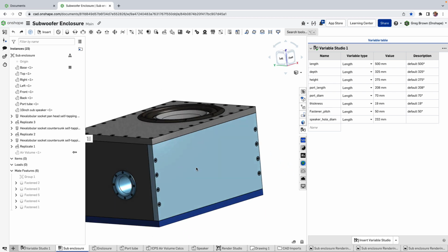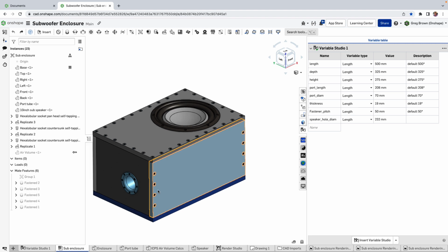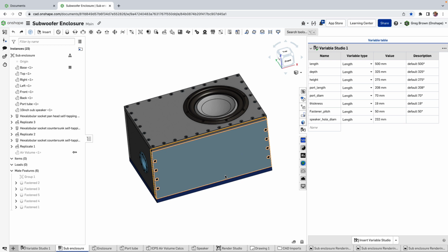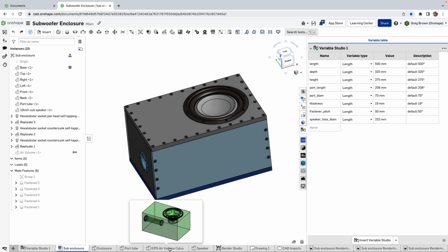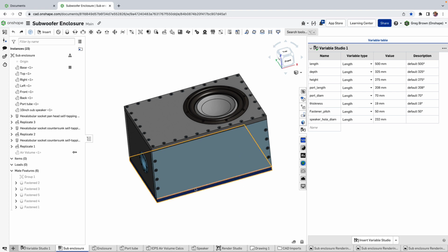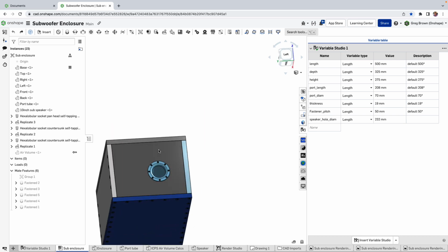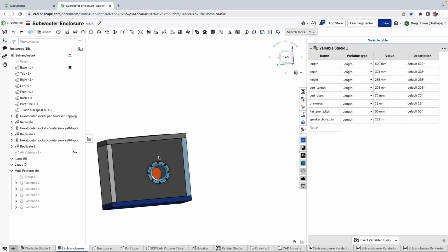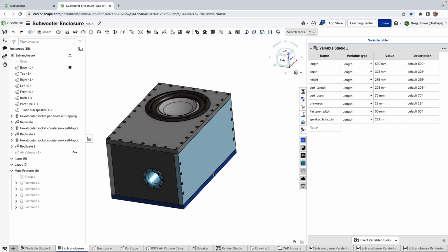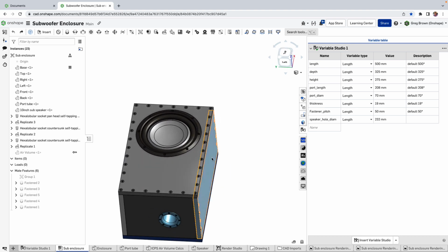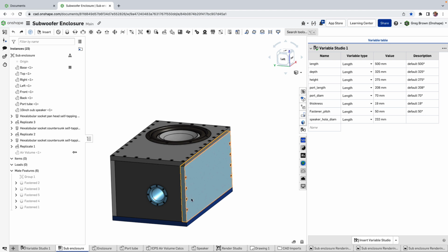And we get back to our more modestly connected, and I think it's going to be just fine like this. Now, just as one final bonus, I am interested in calculating the resonant frequency of this, because this is kind of what it's all about. You want the resonant frequency of this box, the air in the box, to be around 32 hertz. Perhaps that's a goal typically for an automotive subwoofer of this 10-inch kind of size. So how would you do that?